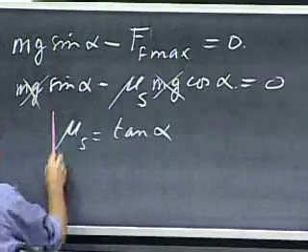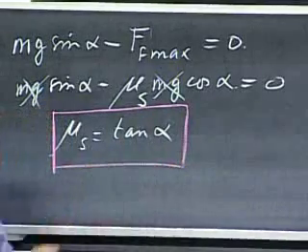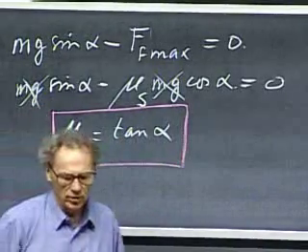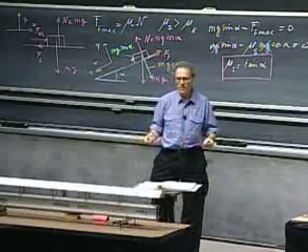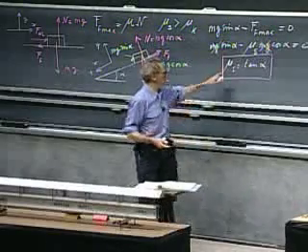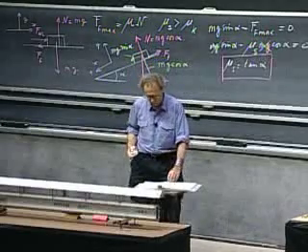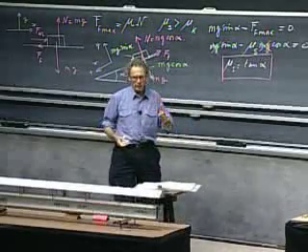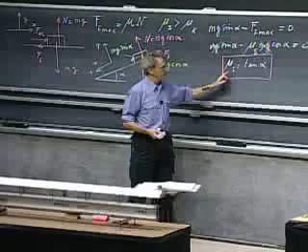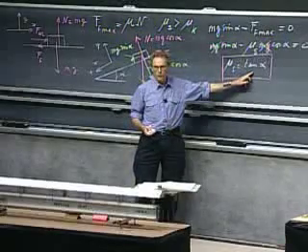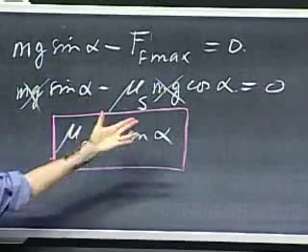It's that easy to measure. So you increase the tilt. We will do that later until it starts to slip, and then at that critical angle that it starts to slip, you have a value for mu_s, for the static friction coefficient. It is very non-intuitive that this friction coefficient is completely independent of the mass. The mass has disappeared.